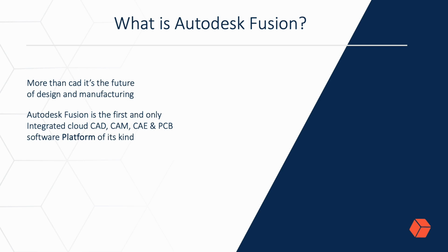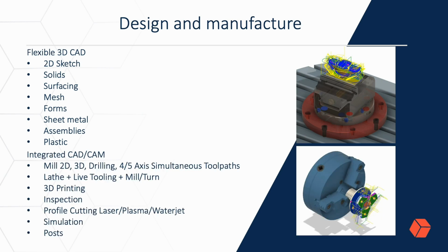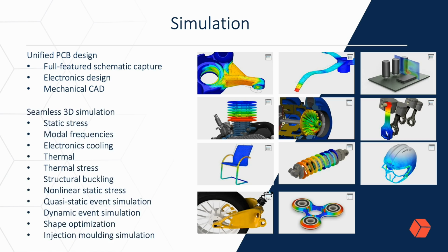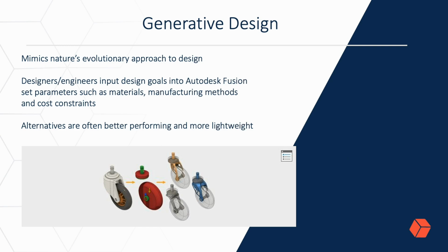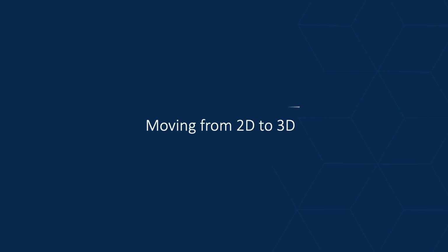We'll now demonstrate how to move from a 2D sketch to 3D geometry. Firstly, we specify which work plane we want to create the sketch in. Here we will be creating a spiral with which we will create our 3D geometry. We can parametrically input the values of our spiral dimensions. This drawing workspace, you will see, is very similar to your standard 2D CAD package.